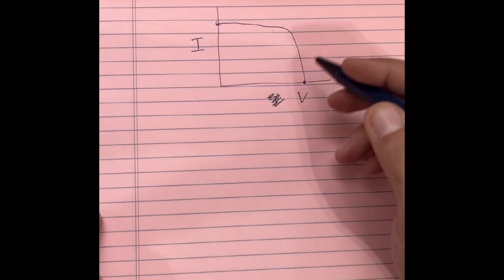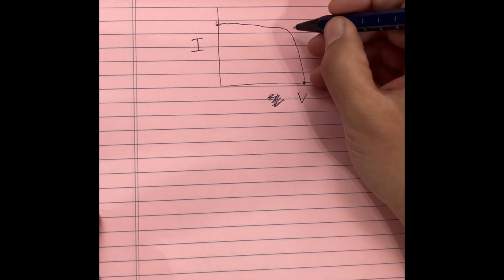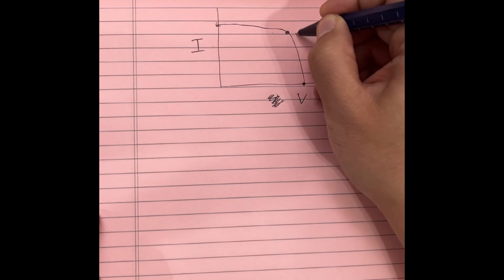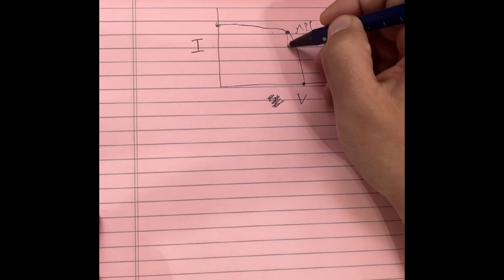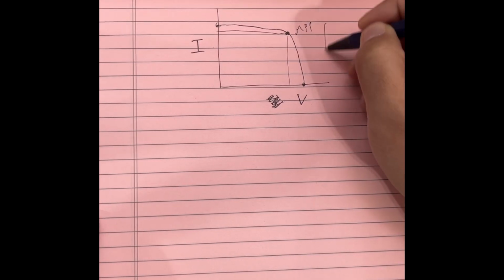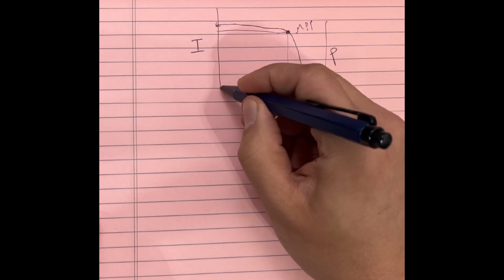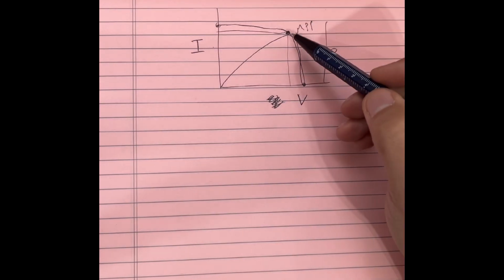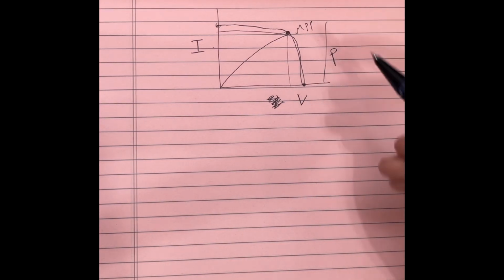Those are two values that you'll see in a data sheet for a solar panel. And you'll probably also see this IV curve. And what's interesting about this is the power is I times V. So it's sort of this furthest point over here where I and V are maximized, and you get your maximum power point. And since it's the area of this rectangle, that is the amount of power you're getting. So if you put power on this axis over here, then your power curve kind of looks like this. And the idea is that if you want to harvest the maximum amount of power, your solar controller needs to operate at the maximum power point. And it can do that by basically changing its current draw until it hits this point right here.